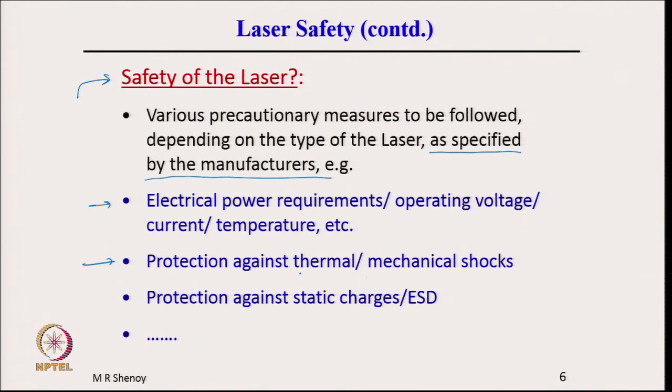Thermal shocks, sudden variations in temperature, can also damage the laser material. Then there is protection against static charges, ESD, electrostatic discharge. This is very important, particularly for semiconductor lasers, where it is crucial to take care of protection against static discharges.